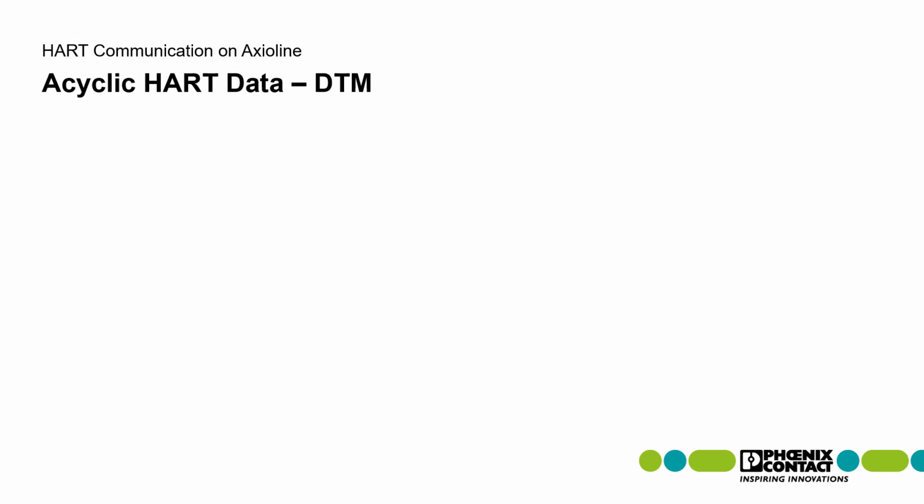All right, so now we're going to talk about acyclic HART data in terms of DTM, device type management. There's two different ways to really talk about the DTMs and acyclic data through DTMs when we're talking HART for Phoenix Contact. And the first is Startup Plus. Startup Plus does not get you that HART data.